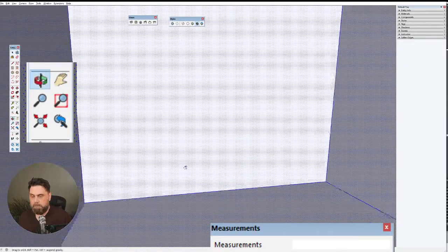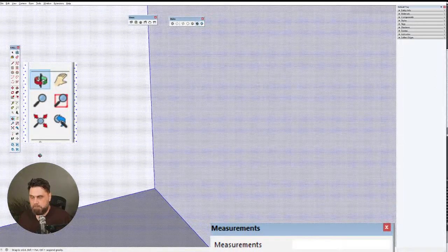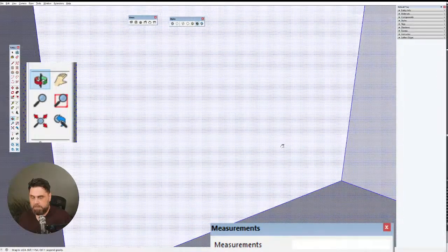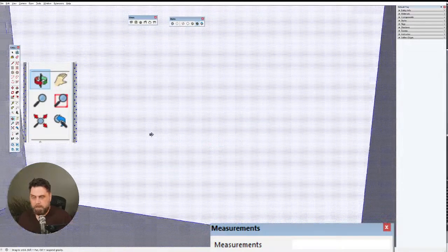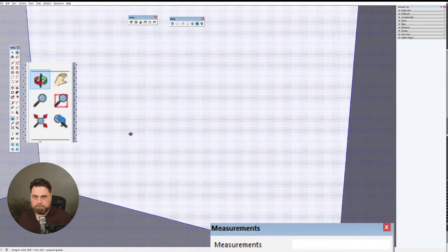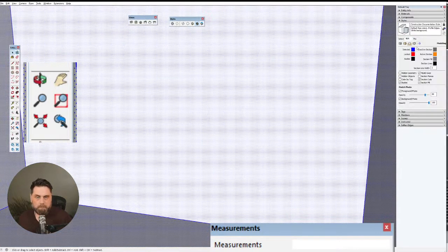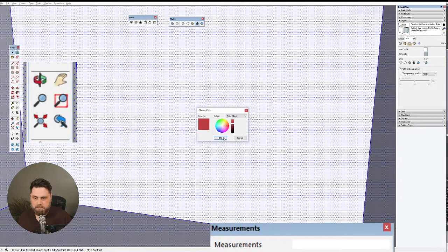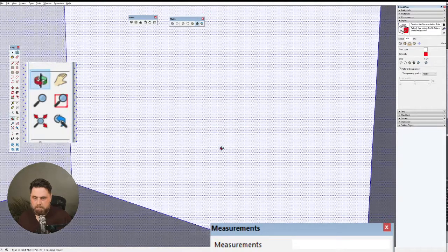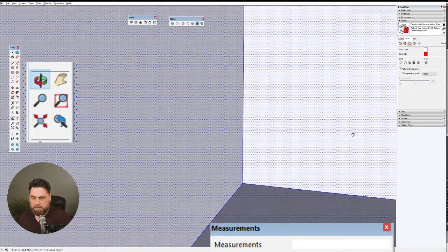Okay, so we're in the wall though, we're inside the cube. And now I just want you to rotate around and practice this without getting stuck or going through the wall like that. Actually, why don't we go back into our styles, go to edit, face style, and turn the back color red just so we can see it right away. Let's do a bright red like that. So then if we break through, it's like instant red. Okay, and then practice.